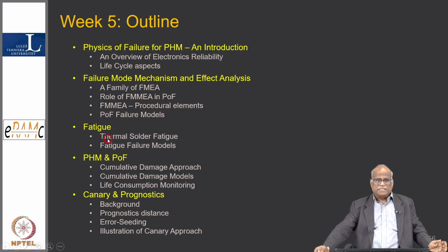We discussed fatigue, thermal solder fatigue, and metallization, because of CTE or temperature alone. Those properties, and fatigue failure models, we saw in terms of damage, PHM and POF. Then we saw the cumulative damage model, then life consumption monitoring, and lastly canary and prognostics: background, prognostic distance, error seeding, a beautiful mechanism to develop a canary, and an illustration of the canary approach.